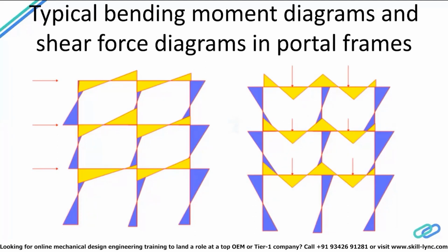So these were the few items I wanted to touch upon in terms of bending moment and shear force diagrams. Obviously, this is not an exhaustive type of loading. For example, I just considered point loads as of now, but a structure would also see a bunch of uniformly distributed loads, which is what dead loads typically are. They have a more or less similar behavior, but the difference is that here we are seeing these discrete lines, and when you consider a uniform load, this will become more like nice curved lines.